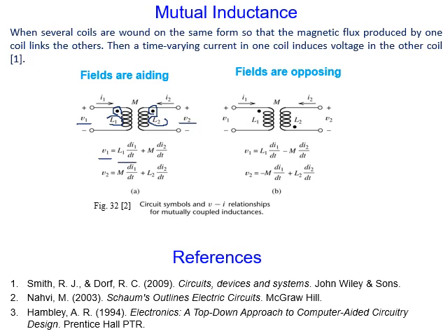That's fine. But what do we also add? We add the effect of the other inductance, L2, by multiplying M di2 over dt. It means there is another inductance close to L1, affecting it, and the current flowing through the next inductance, which is i2, will affect it. M is the mutual inductance. It means for each inductance there is a self-inductance, which is L, and there is a mutual inductance, which is M. Both of them are in henry.